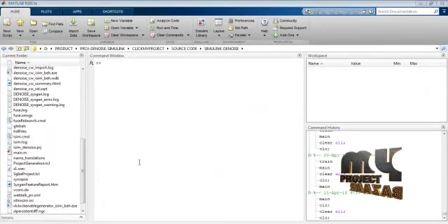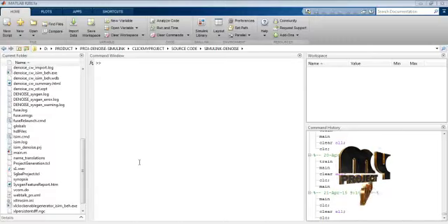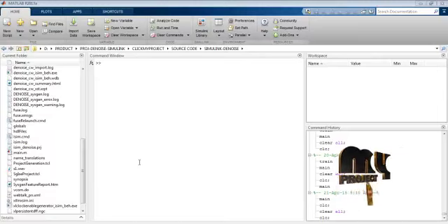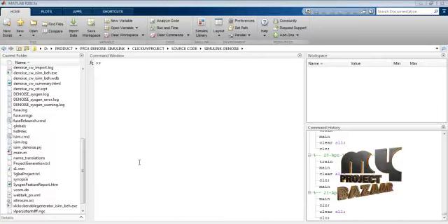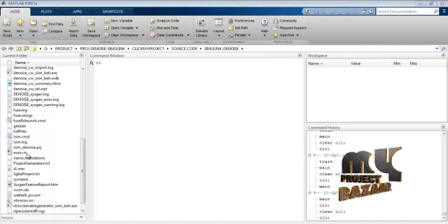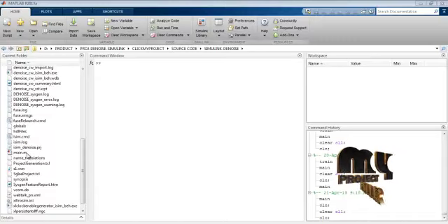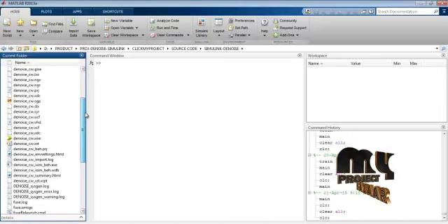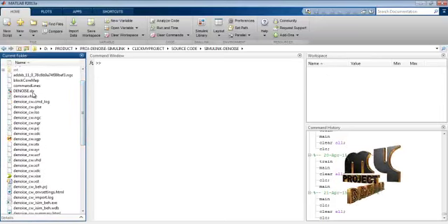Finally, we see the output for the product. This product combines MATLAB and Simulink, then goes to the Xilinx design. These two software tools are combined in our processing. Then we browse the input signal and combine it with the main M file function. Then we add additive white Gaussian noise and amplitude noise to our input voice. Then we apply the noisy signal to the denoise Simulink design.